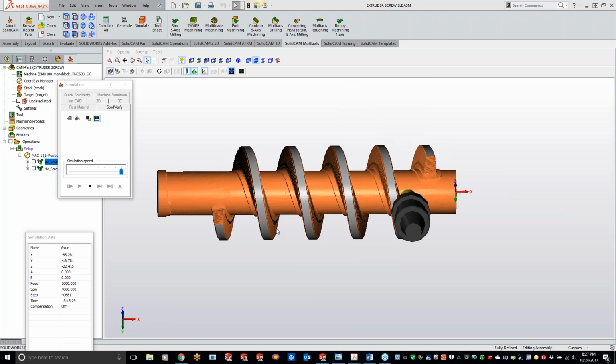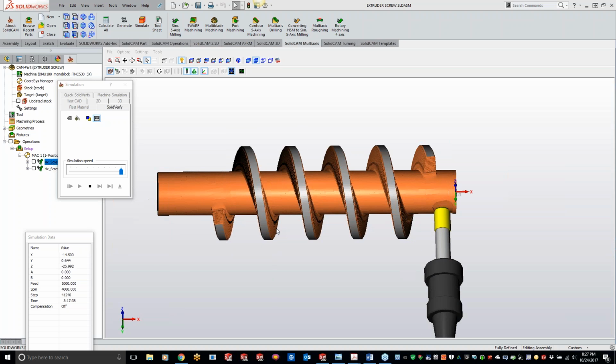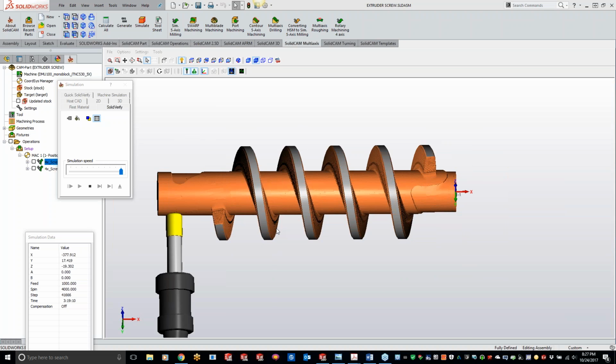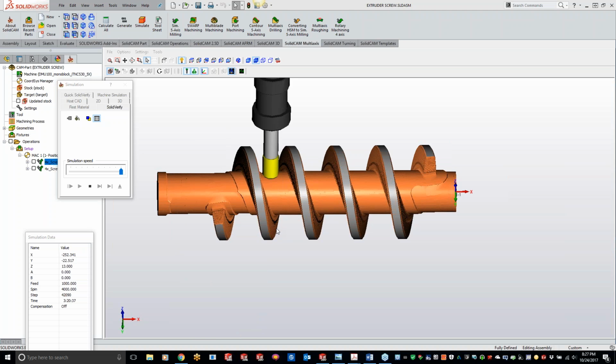One thing we could do to combat that is, if your stock or your shaft is square, which I 100% see happening, we could set up a circle so it roughs it out so all the points of that square line up around that circle, then we're roughed out, and then we can come back with the finishing.